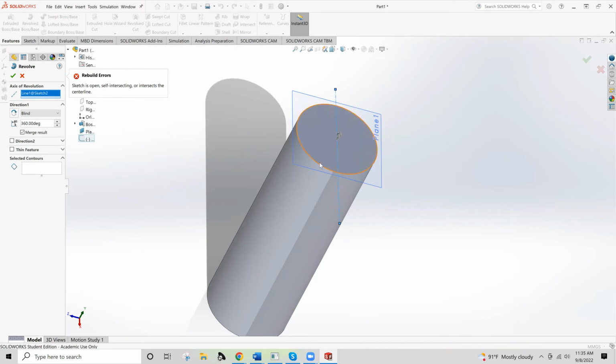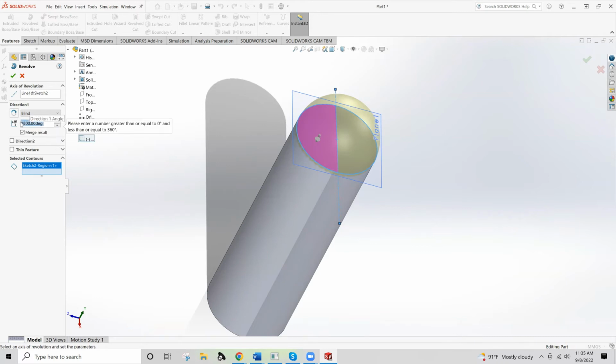If we're trying to rotate this whole object around 360 degrees, that means taking the object itself and revolving the whole thing 360 degrees, which creates the same internal volume approximately 4 times rather than just once. Because of that self-intersecting internal volume, you're going to have a lot of problems with it. So instead, you want to select contours. If you just select these contours and then tell it, I actually only need 180 degrees, not 1800.